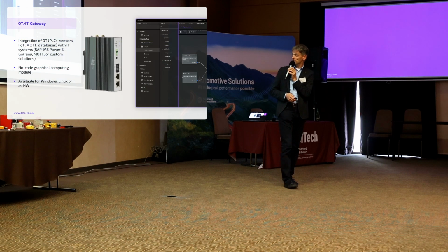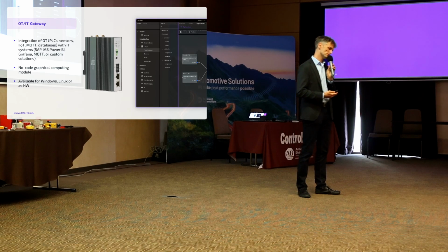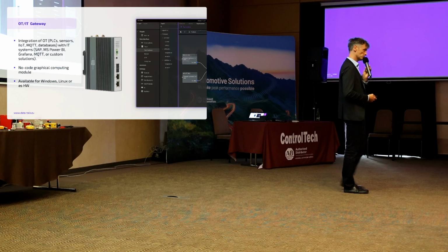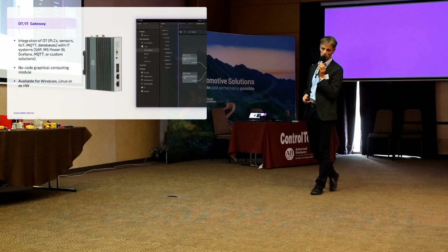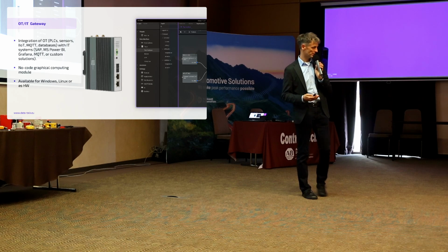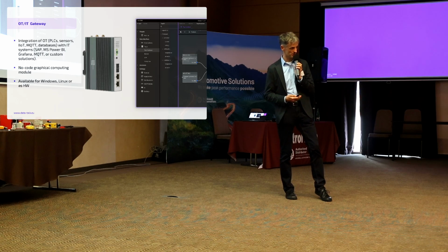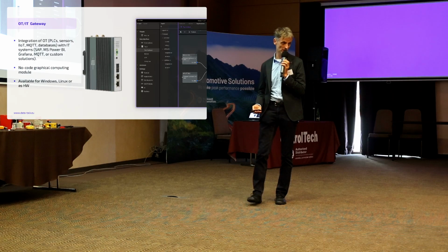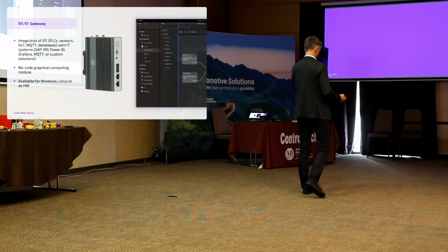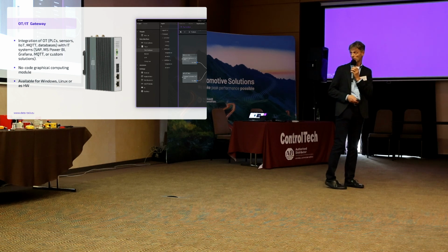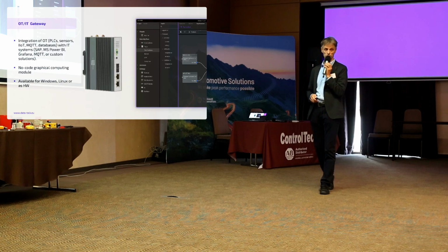And the last product, very shortly, OT IT Gateway. This is the product which can take data from OT technology like PLCs or sensors and send them to IT. So, a very easy example: you have some production, this system takes the production data from the PLC and stores it into your ERP system. It can be SAP, it can be Abra, it can be whatever system, or sends them to the cloud, whatever is possible. Also, this can work as a security gateway between OT and IT technology.